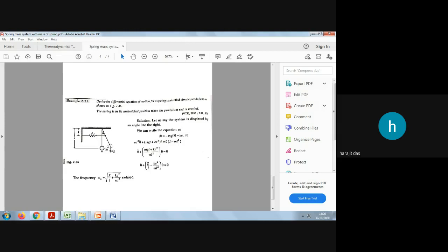Another force which will act because of the stretching of this spring will act from the right side to the left hand side, because this is stretched. So on the spring, one leftward direction force, meaning a compressive force, will act. What will be the value of this compressive force? The spring constant is K.